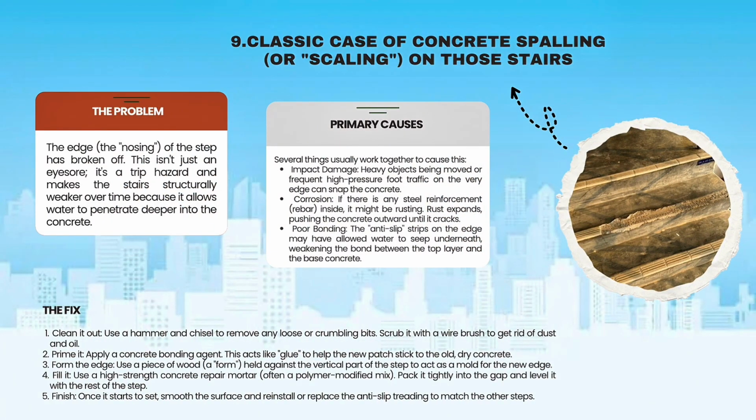Okay, 9. Classic case of concrete spalling. The problem is the edge, the nosing of the step, has broken off. This isn't just an eyesore, it's a trip hazard and makes the stair structurally weaker over time because it allows water to penetrate deeper into the concrete.